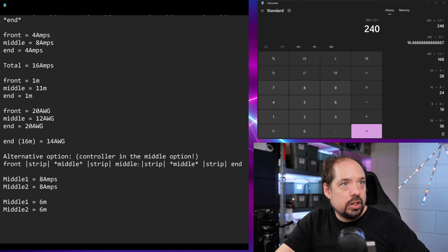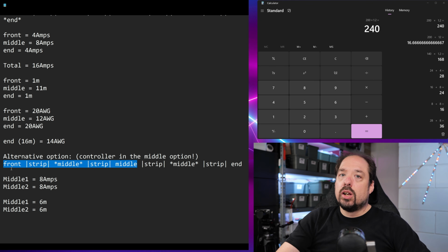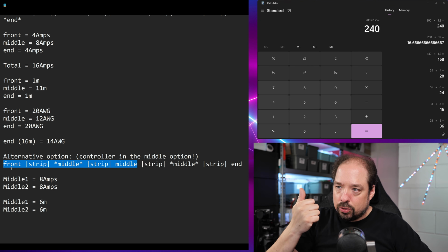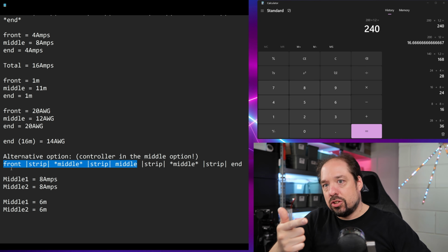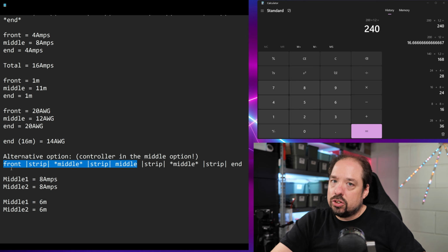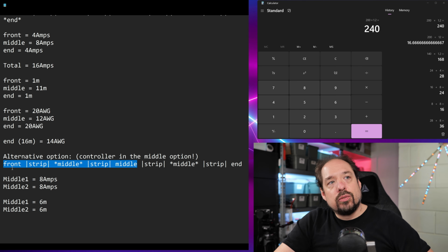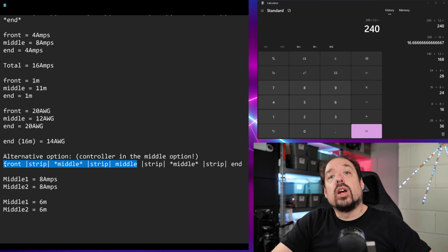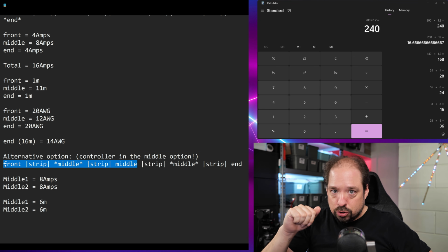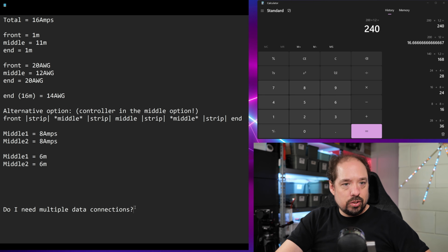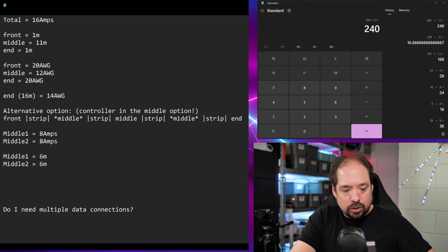Of course, you're going to need a data wire that's going from here to there, but with a Dig-Quad or a Dig-Octa system with their built-in level shifters and resistor switchers and things like that, having a 10 or 11 meter data cable generally is no problem. I would advise to run a data cable and a ground cable next to each other, so a 2-wire cable, and then flip that channel to 33R mode. What the hell am I talking about? I'll talk about that a little bit at the end of the videos.